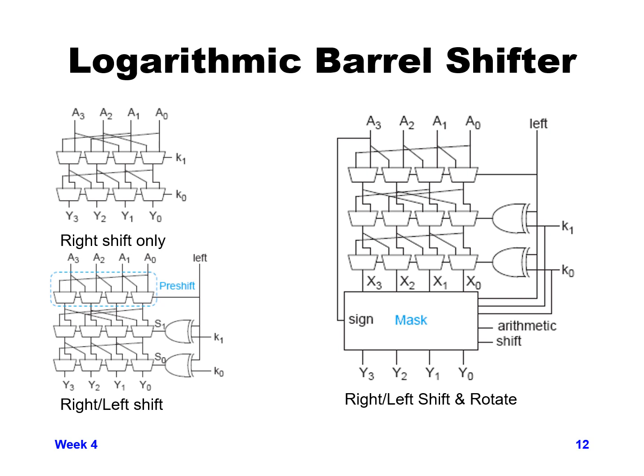So that's showing how to do a left and a right shift with this pre-shift and then the XORs of the K value by the left value. And then finally, on the right-hand side, we have the left-right shift functionality in the top, and then we have an additional functionality for doing our mask bits and sign bits, and I'm not going to go into the details of what the combinational logic is in there, but that will allow you to do the equivalent of a shift as opposed to a rotate.